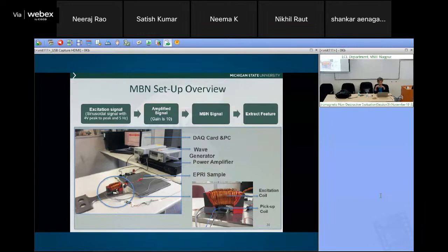Thickness of the material? It is almost an inch thick. Yeah, well, this is also a surface or near surface. I don't think it can go very deep, because if the defect is down there, the leakage flux at the surface is going to get smaller and smaller. So yeah, and it has to go.